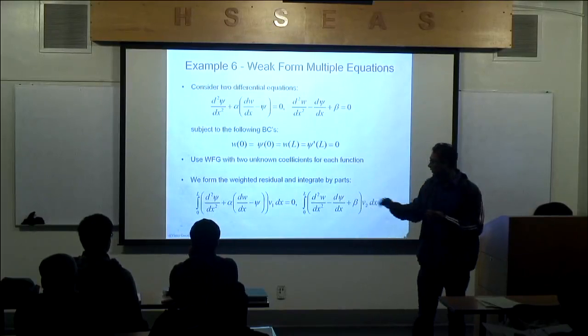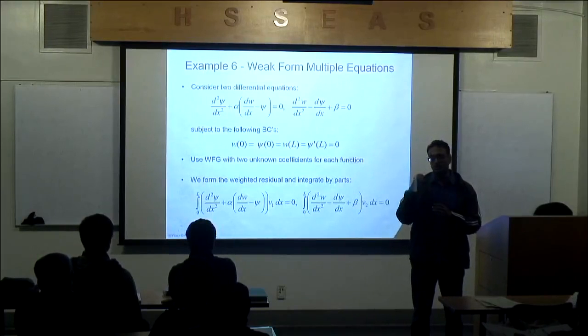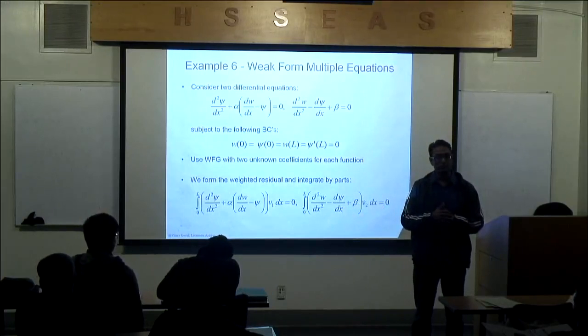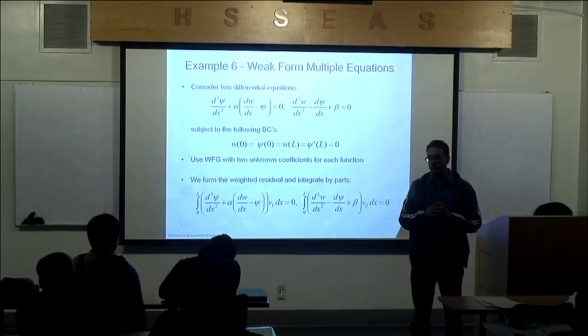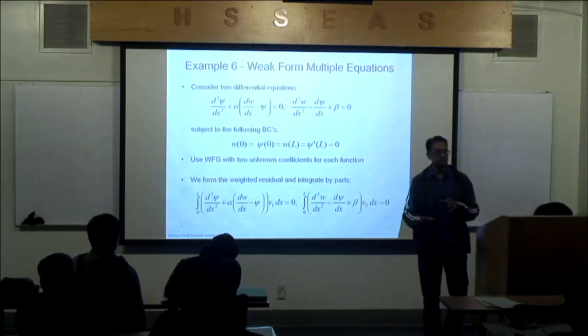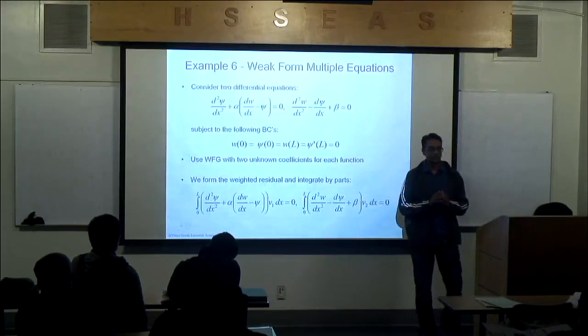But with weak form Galerkin, what do I need to do now? Reduce the order of differentiation. So I want you to learn these terms: weaken the continuity requirements from second order to first order. I split it in half. If I have a fourth order, I go down to second order. Yes? And the approximation function only needs to satisfy the essential boundary condition, unlike strong form Galerkin, where it satisfies both essential and natural boundary conditions.